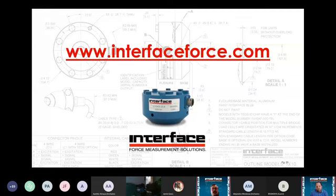I would say one of the problems you might have is mechanical installation issues. We kind of talked about it. It's just like a nut or a bolt, really. So it's just a threaded connection, but there's actually a lot more to it. People kind of discount how important it is to make sure you have things aligned properly, that you don't have any parallel load paths, because all of the load has to go through the load cell to make a proper measurement. So if you have a plate and the plate's riding on the heads of the screws of the load cell, for example, that's going to shunt the load past the measurement. So really, people don't put enough weight on how important mechanical installation is, I should say.